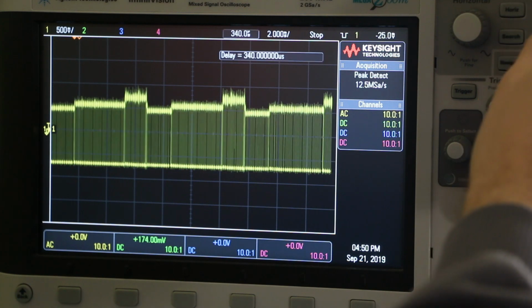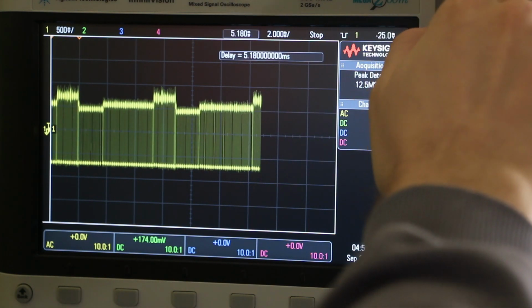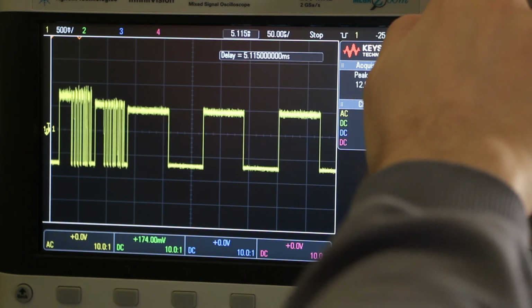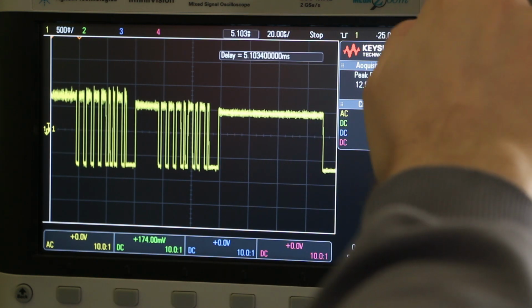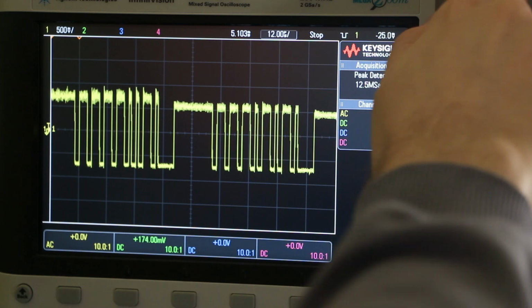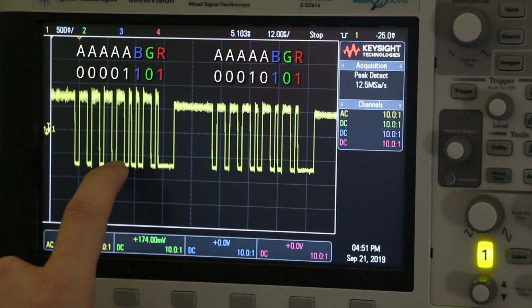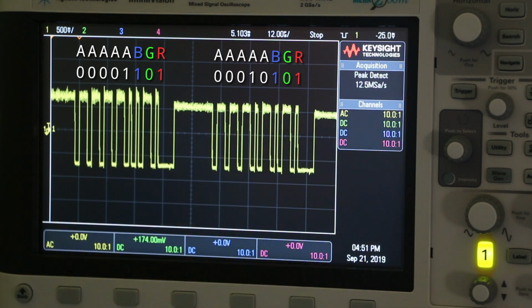If we adjust the horizontal position and zoom in, then at this point we'd expect to see two commands coming through, turning both the odd and even pairs on, and sure enough, here it is. So what we see here is that we're using the LEDs configured for this purple, and we can immediately see now that both the address 1 and address 2 LEDs are being configured for purple.